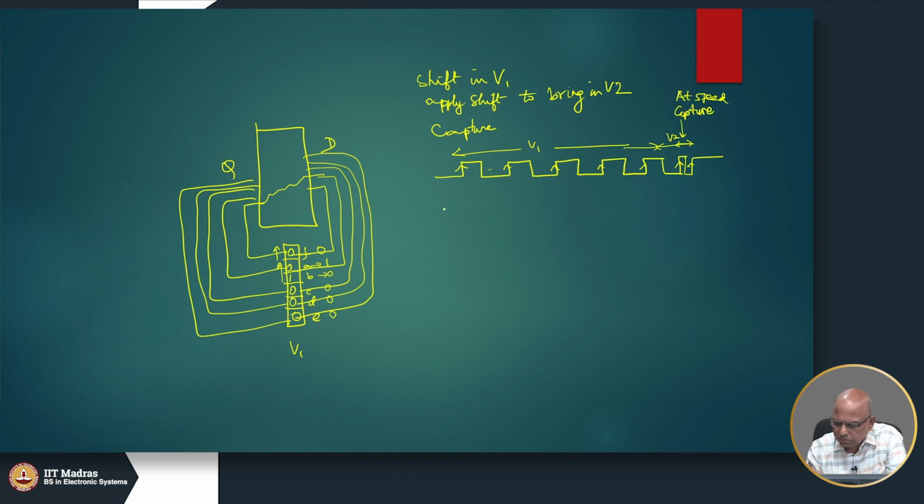So here the scan enable signal was high in order to shift, then it remains 0 for a very short time and comes back. So till even V2 we are shifting only, okay, whereas in the previous one V2 was captured.